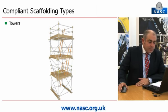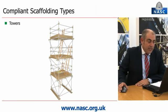Towers, we see changes to the safe height to base ratio calculation for static towers erected externally or with a wind load. We see compliant scaffolds for lift shafts, but mobile scaffolds in tube and fitting are no longer included.